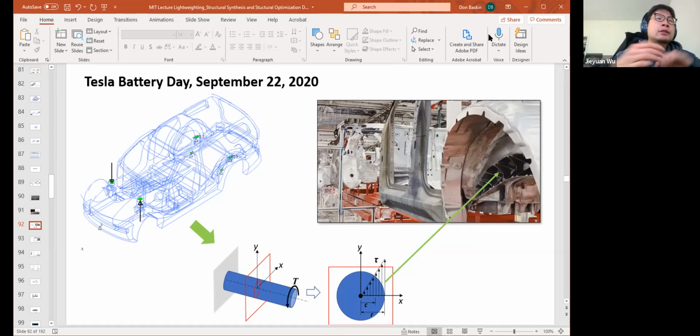Would you be worried about torsion? Because essentially you have two sheets, and if there's no strengthening mechanism crossing both directions, it might actually be weaker in torsion than the traditional structure. Well, if you think of the neutral axis of torsion going through, say, the center of the driver's seat, imagine a line in the middle of the car, as high as wherever the center of the polar moment is. Let's say it's about halfway up the seat structure, crosswise in the middle of the car. You imagine that's the axis of torsion, right?